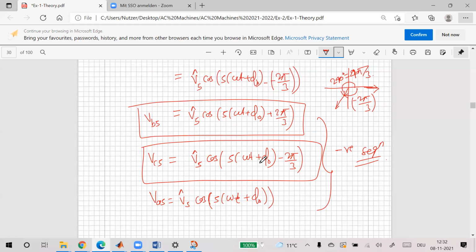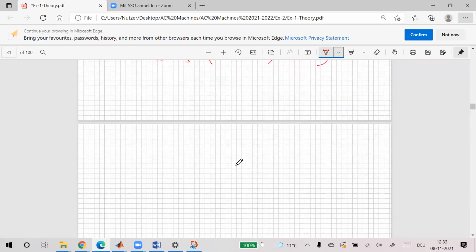So if you want to see the DQ transformation for fifth order harmonics, then what would you expect in the DQ frame? AC component. Frequency of 5 times the frequency of the generator. Not 5 times, 6 times. Because for negative sequence, it's omega 1 plus omega 2. Omega 1 is 5 times, omega 2 is 1 time, so it's 6 times. So you see, 6 times means your 300 hertz. Okay? Let's see the seventh order harmonics.